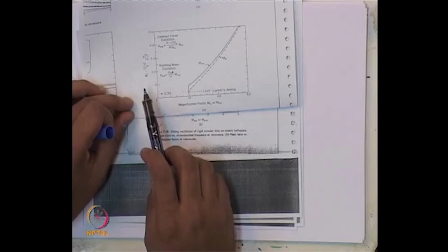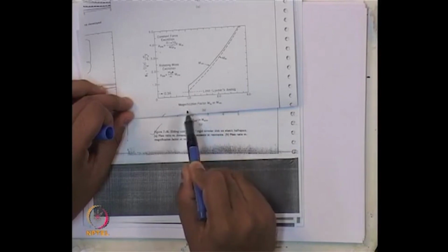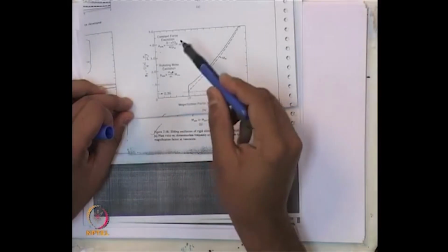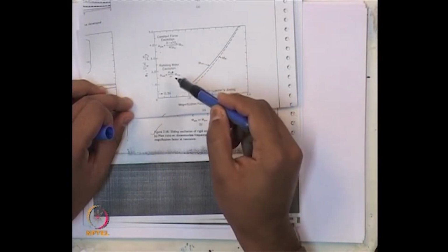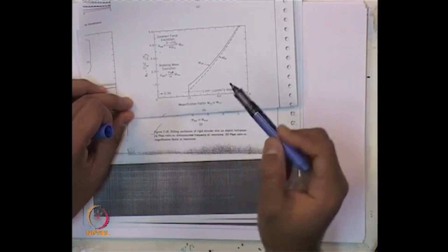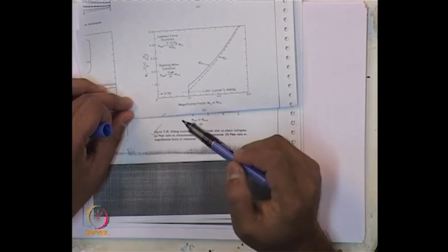I had shown earlier. BZ, consider the vertical mode of vibration. Now, this BZ value we have computed for 3 different types of soil, from which we can compute magnification factor MM or MRM, whether we are considering constant force type or rotating mass type excitation. And this is the equation we need to use to get the value of displacement amplitude. So, this dotted line is for constant force type excitation and the solid line is for rotating mass type excitation.